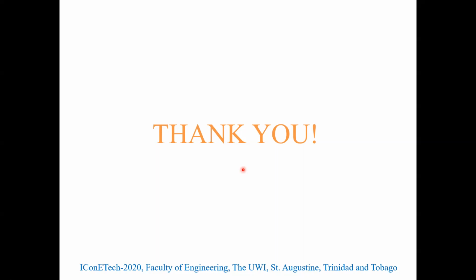It affects all parts, but PLA has the most prominent effect, where you could print a part out of PLA today, leave it out, and by tomorrow it absorbs enough moisture that it's brittle to the point where if you try to cut it with, say, pliers or something, it could shatter almost like glass. So that's why I had to take so many precautions during the building and during the storing.